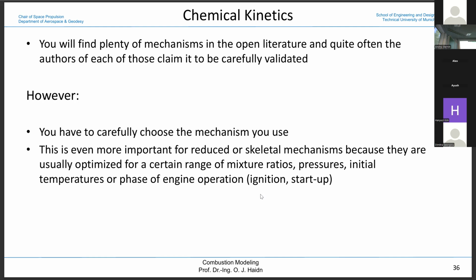Then they say, okay, I have a Damköhler number. If it's near 1, meaning that fluid and chemistry are playing in the same league, they need to take into account finite rate chemical kinetics. If the Damköhler number is very high, then you assume chemical equilibrium. And then they need to take into account what happens if temperatures are low, that there is no chemical reaction. Flamelet would say it doesn't really know about the time scale, so it needs to see the equilibrium.